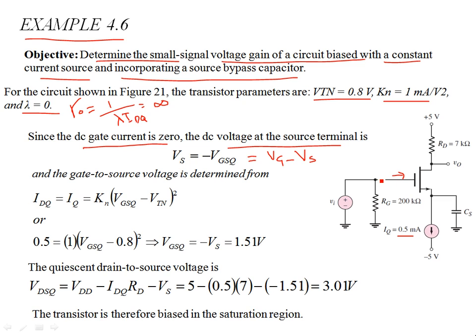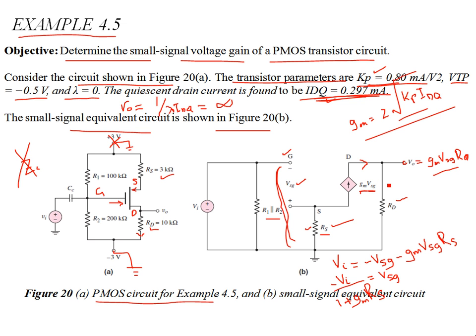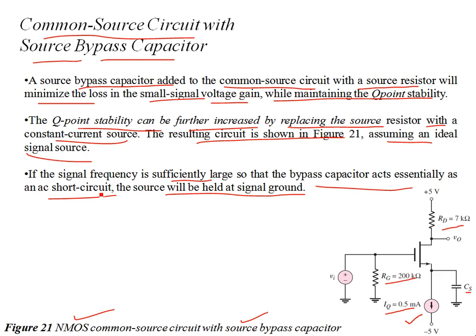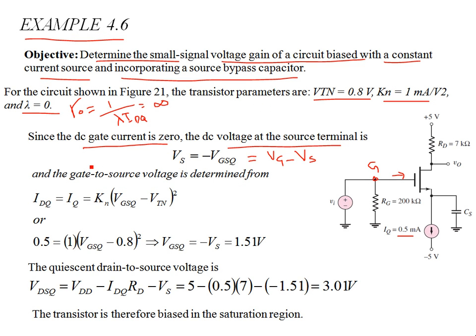There is no DC biasing at the gate terminal, and there's no biasing resistors R1 and R2 like we had previously, which act as a voltage divider and establish the gate voltage owing to the plus minus 3 volt sources. So there are no such sources, there are no biasing resistors. So you see VG is essentially 0. So VS can be written as minus VGSQ.